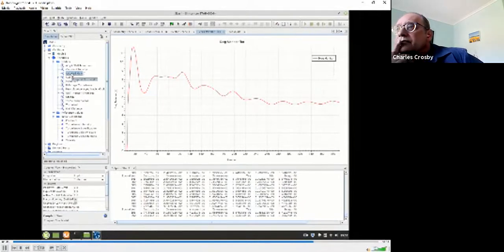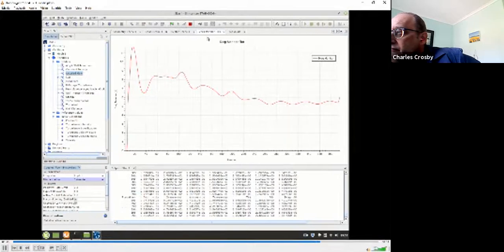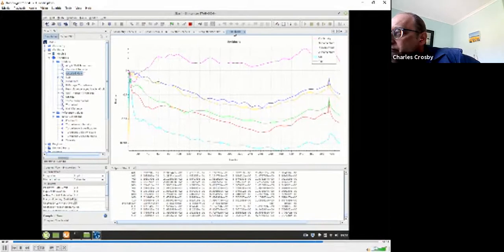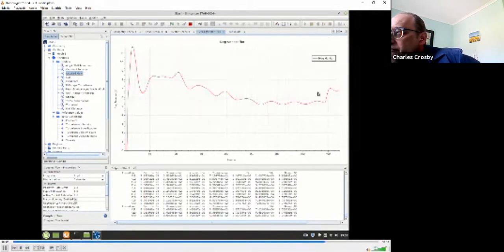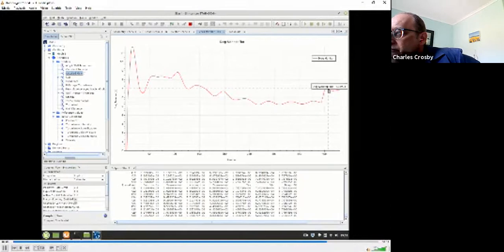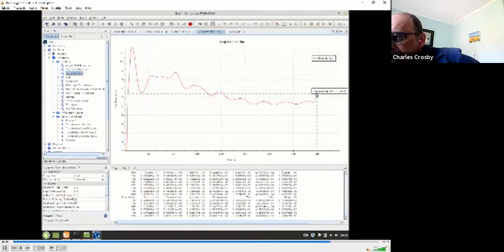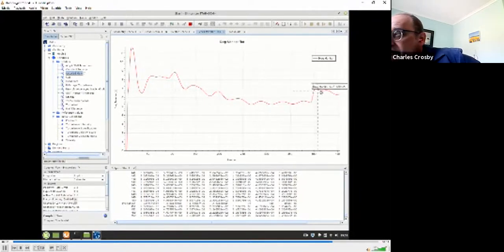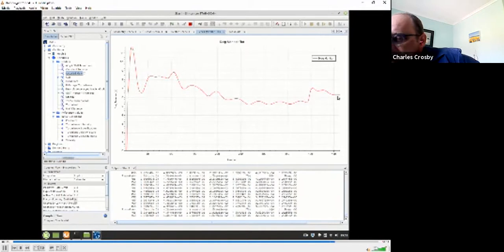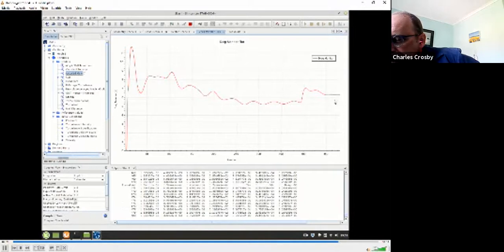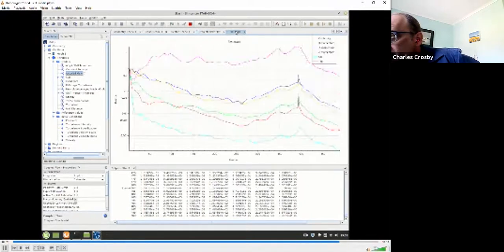We can take a look at the properties of the coupled flow, and we can change to first order upwind differencing as we've done before. And once again, you'll almost certainly see a much more stable calculation with the residuals coming down very nicely, and you can see an immediate difference in the answers when we went from second order differencing to first order differencing. So you never really want to use first order differencing for answers. It is not as accurate. It's stabilizing quite nicely, but at a different value.